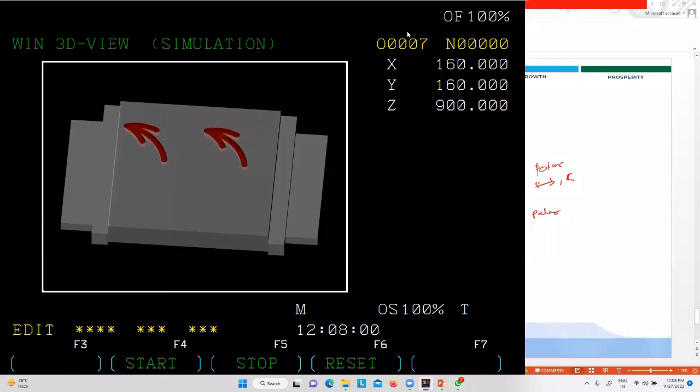CAM designing software is already there, so how is this different? Actually, in CAM the G codes and M codes are generated automatically. But are they correct or not? How will we know that? With the help of these coordinate systems and these manual machines, you are going to know whether it is correct or not.